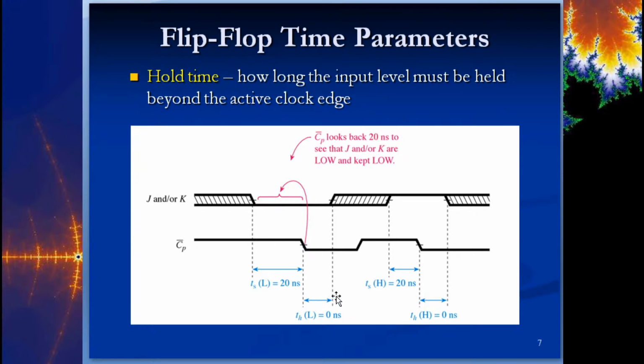Some chips do have a hold time. A lot of them, however, do not. They've advanced the technology to where it just needs to be stable before the trigger happens and not necessarily afterwards. If it's set up beforehand, then it's fine. So I just wanted to point out that sometimes the hold is a 0 nanosecond hold. It just depends on what the data sheet says.